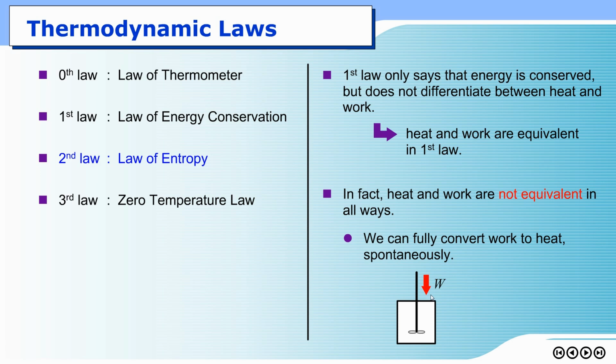Increase in internal energy should make the temperature of the system increase, because temperature is an indicator for internal energy. Once the liquid here has higher temperature than the surroundings, there's a driving force for heat transfer from the system into the surroundings, like so.